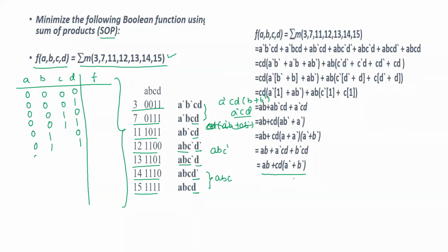That is not acceptable as far as an implementation is concerned, because any error will lead to the number of gates being on the higher side, and your area is more, and power is more. Also, your circuit may malfunction if some algebra is not solved properly, so there are always chances of making some sort of errors.